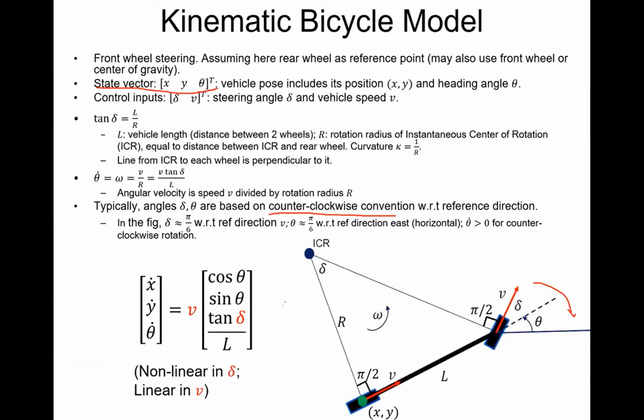So somewhere you have a global point of 0, and somewhere you have a global direction of 0, for example, east. It doesn't matter how you define the global coordinate. The point is that they're global. They're in reference to a global reference frame. And then the steering angle delta is in reference to the vehicle's heading direction. So delta is kind of in a local frame. Yeah, and the error is if you're to the left of the road or to the right of the road.